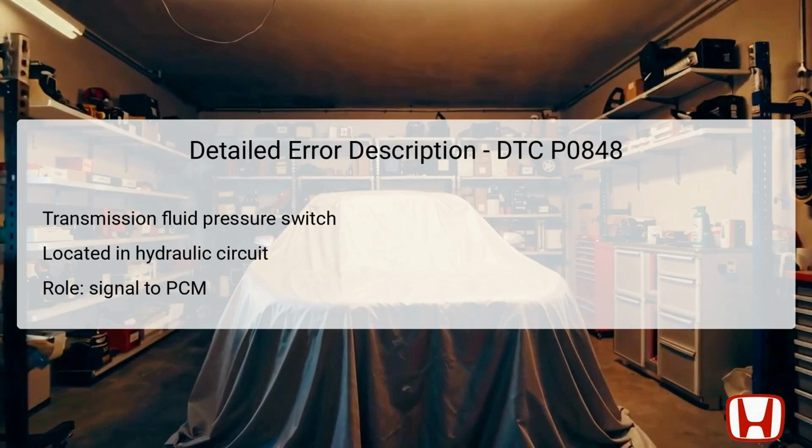The transmission fluid pressure switch B, involved in DTC P0848, is installed precisely in the hydraulic pressure circuit that leads to the third clutch of the Honda Accord. Its role is vital. It ensures that hydraulic pressure is effectively supplied to the third clutch when needed. Proper engagement of the clutch is essential for smooth transitions between gears, particularly the shift from second to third gear. The switch's location is strategic within the hydraulic circuit, making it integral to the overall functioning of the transmission system.